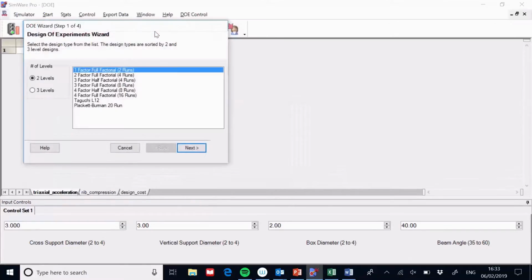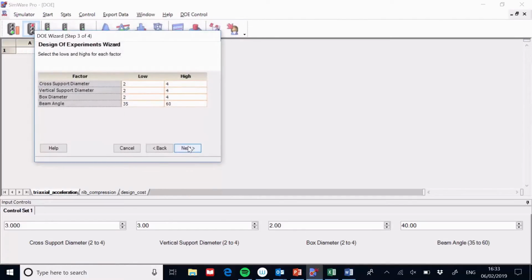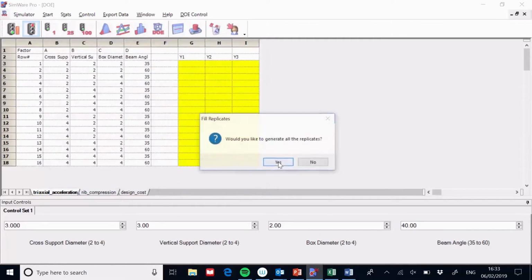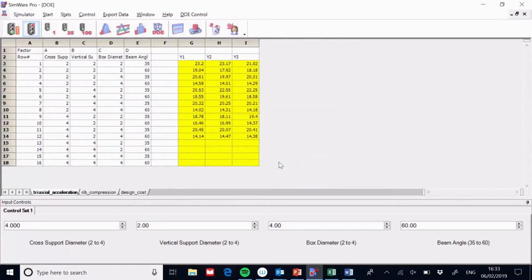Now what I need to do is to simulate us doing an experiment. Now because there's 4 factors, the experiment we're going to do is known as a full factorial. So we're going to do a 16 run full factorial design. And this thing is just going to create some data for me, going to create a DOE for me to understand the system that we're trying to optimize.